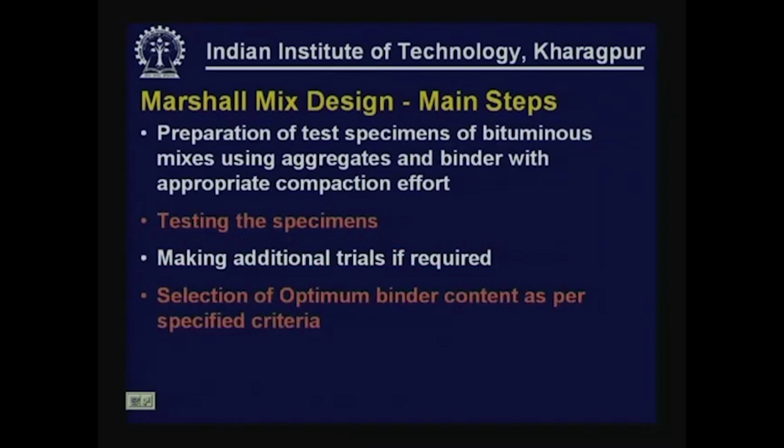The next step is preparing test specimens of bituminous mixes using the aggregate gradation that is selected and the binder that is selected with appropriate compaction effort. We also have to select what is an appropriate compaction effort. Ministry of Shipping and Road Transport suggests a specified compaction effort as per a specified procedure for all highways.